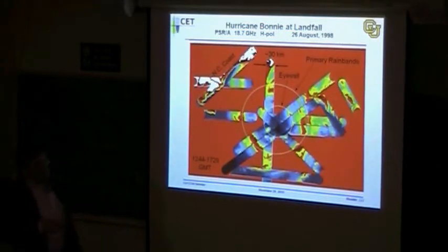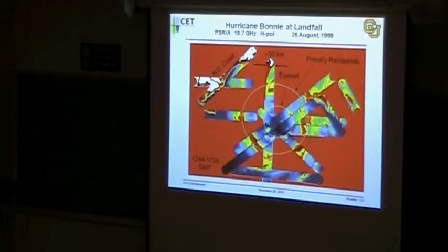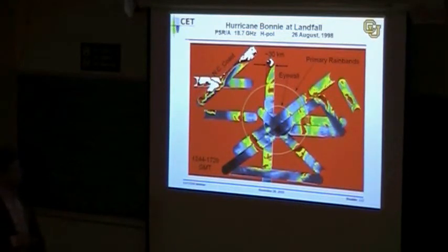Now, why is a kilometer so important with regard to rain? It has to do with the size of rain cells themselves. The atmosphere itself you could think of as a sheath around the globe that has a thickness of about 8 kilometers. And so it's rather natural to think that the size of convective events are also about that same size. There's a relation between the two. You'll rarely find convective events, except, for example, tornadoes, that have extremely skinny behavior relative to this 8 kilometers, or extremely broad, because they tend to decorrelate. So when you can observe things at about 1 kilometer or so, you've observed them pretty much at their native scale. And that's pretty important for environmental observations.